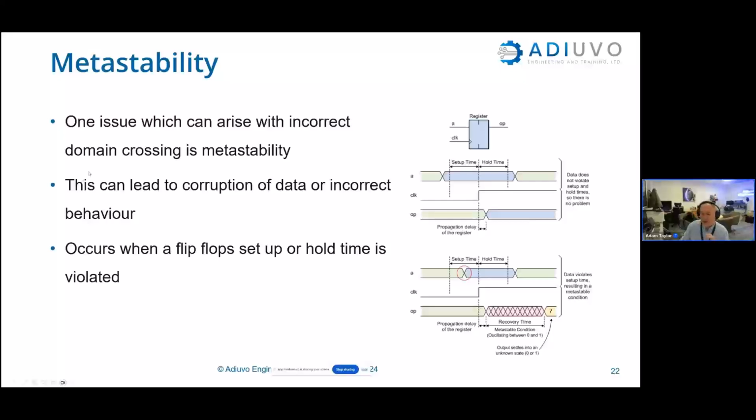That clock interaction report is really good. I think we've actually talked about this. If we violate the setup and hold times, it's part of the reason why we're doing this: for metastability, for asynchronous clocks, and for timing closure. We will get the flip-flop to go metastable and lead to corrupt data.